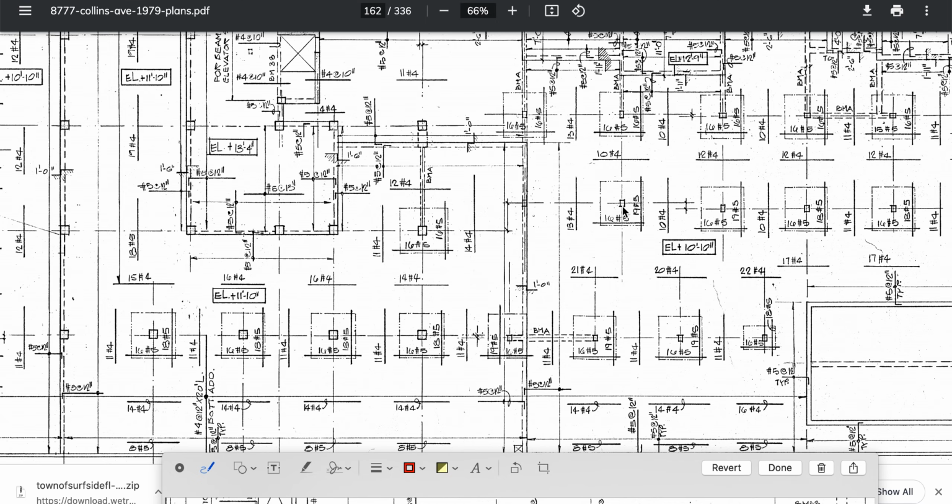I would love for you guys to find it. This is my breadcrumb again. If this is the tributary area, what's the area around the punching shear protection? What is that area called? What is this area called? And once you know that, then you're like, well, wait a minute, it's got to meet that area. But if the steel is going straight, it doesn't meet it directly. It meets it laterally, sideways. In that case, you would need what they call main bars to try to make it over there.